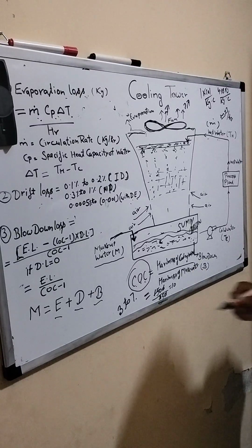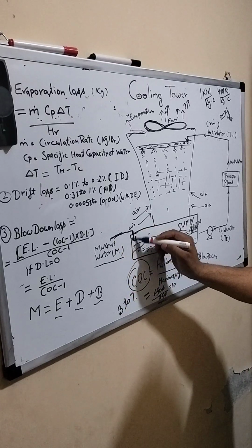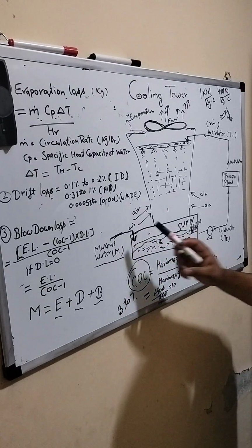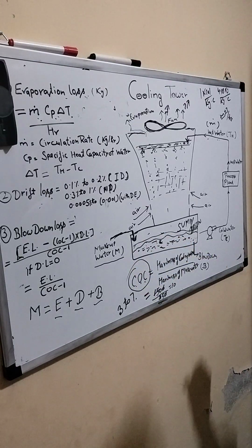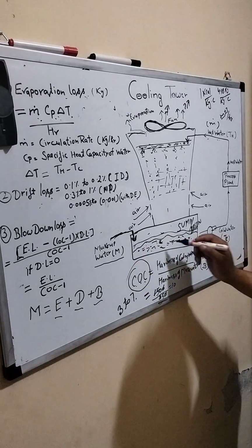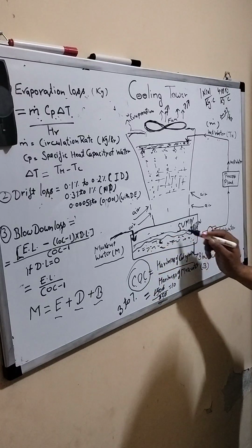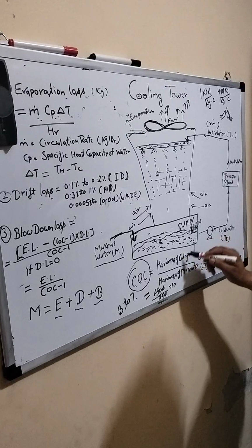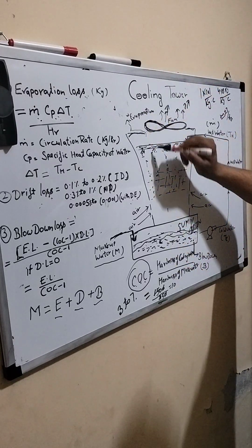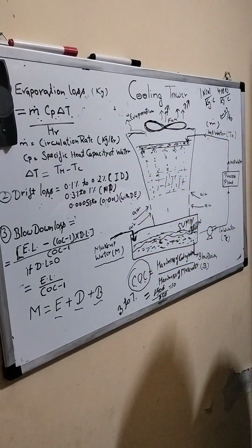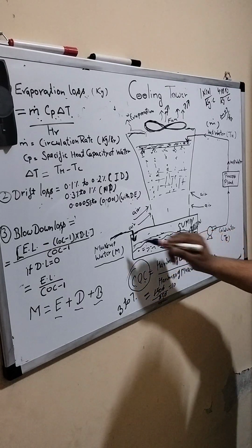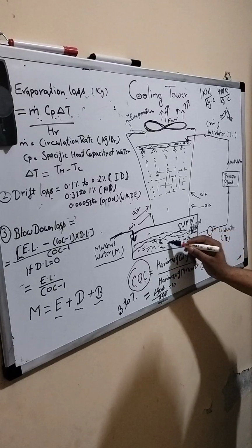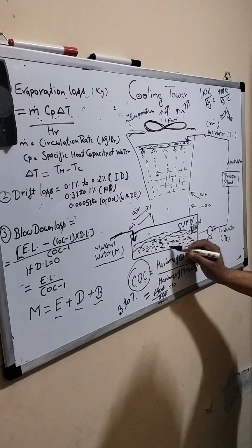What is the need of makeup water? Generally an interviewer can ask why we need makeup water. The simple answer is that if you do not make up the water, the quantity of water will reduce with time because of evaporation loss and some drift loss. The second reason is, if you do not make up the water, what will happen? The concentration of solids and hardness will increase